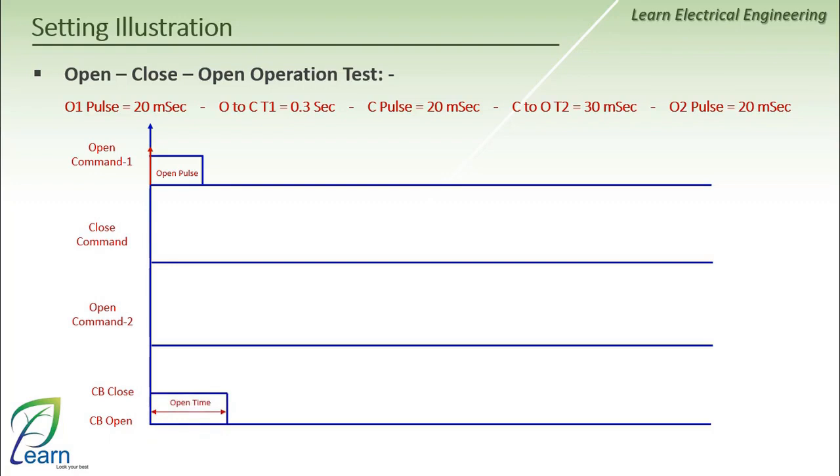We agreed that I must leave a time gap between the operation of opening the circuit breaker and closing it again. This time was written on the circuit breaker's nameplate and was equal to 0.3 seconds. Therefore, my second setting is the time between the positive edge of the first open command and the positive edge of the close command, which will be...